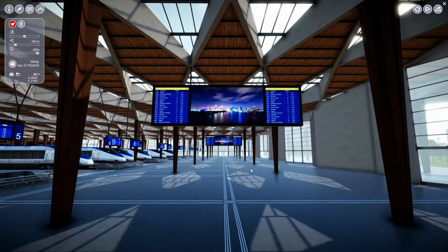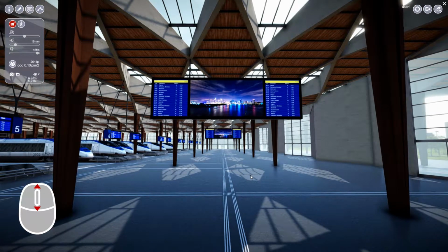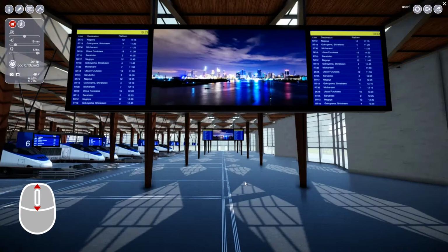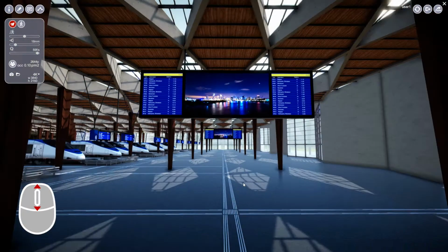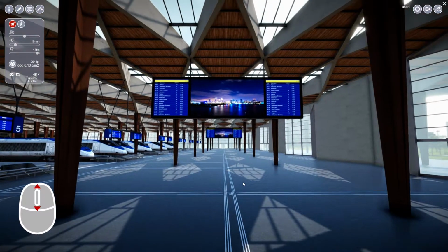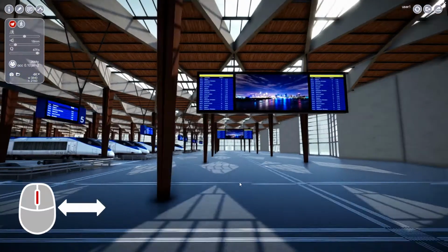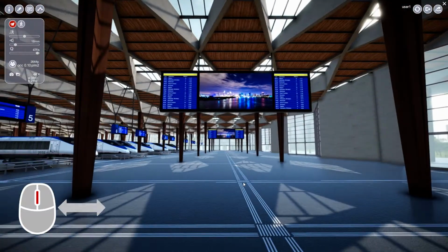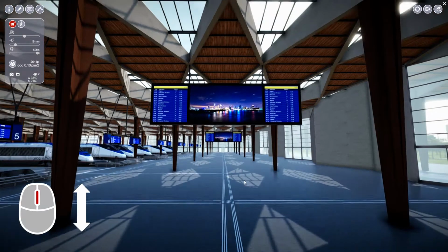The second way of moving is using the mouse scroll wheel to move forward and backward. Now we are moving more like in a conventional 3D modeler, and not with the same smooth, constant speed as before using the keyboard. Holding down the scroll wheel and moving the mouse in transversal direction, we have the lateral movement. If we move in longitudinal direction, we have the vertical movement.